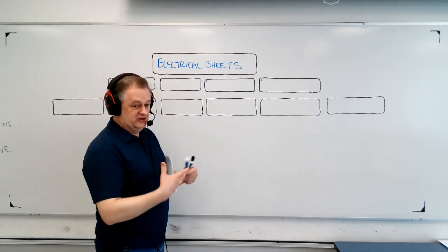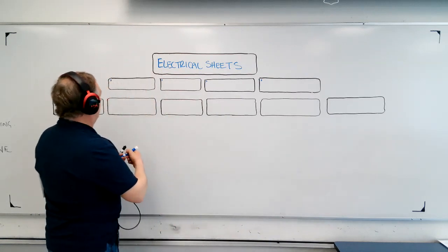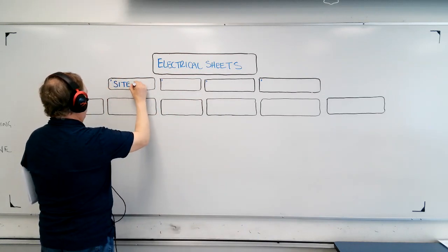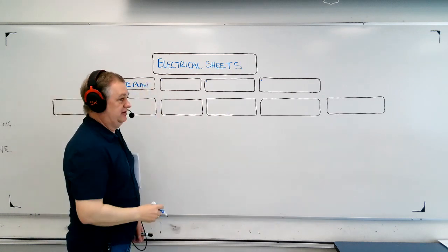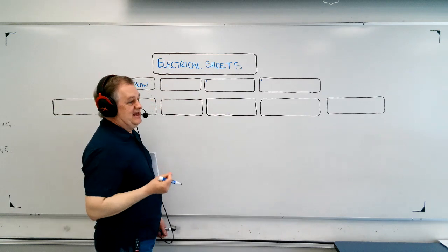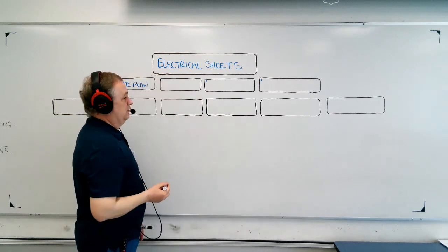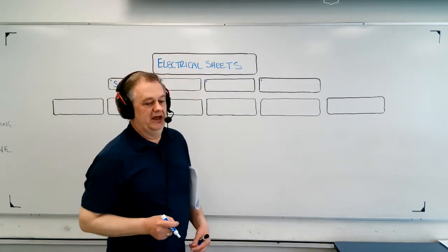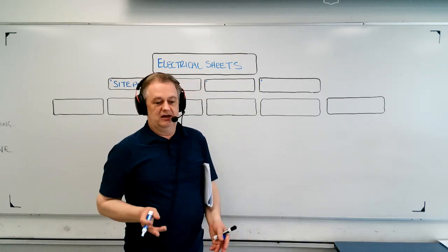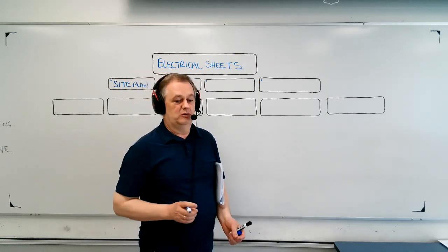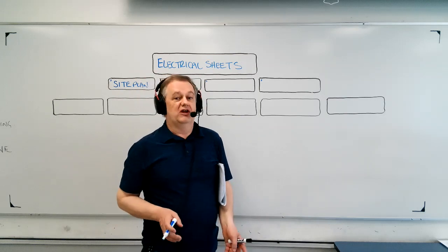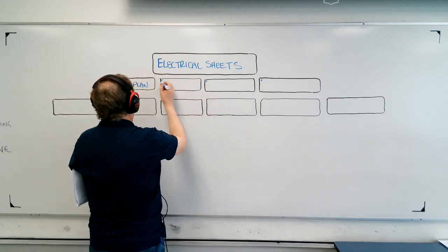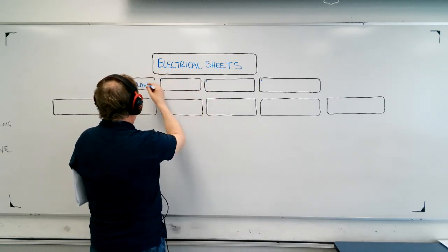the general plans that still apply very much are the site plan. So you'll have a site plan in the E section sheets, and it will show the same site as it shows for architectural, except on this site plan, instead of showing maybe the parking lot spaces and where the sidewalks are, this one will show where the EV chargers are and where the main transformer is for the building, things like that, parking lot lighting. So the site plan, but it will be specific for electrical.